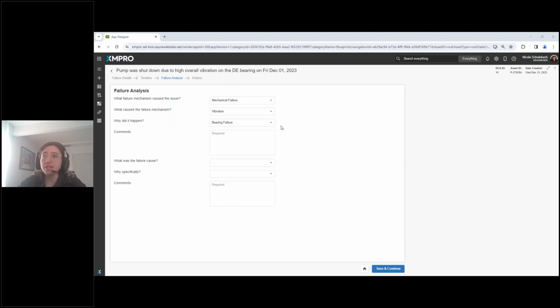Now, what kind of comments or additional information can you provide? You go through and look at your system, maybe your vibe system, and you analyze that data, and you find, like in your timeline, that these bearing readings indicated a stage 4 failure, and then there was indication of BPFO. So basically at this point, your vibe tech has recommended, please shut down. Again, we don't want unplanned outages. Again, this is kind of the higher level, what you actually see.